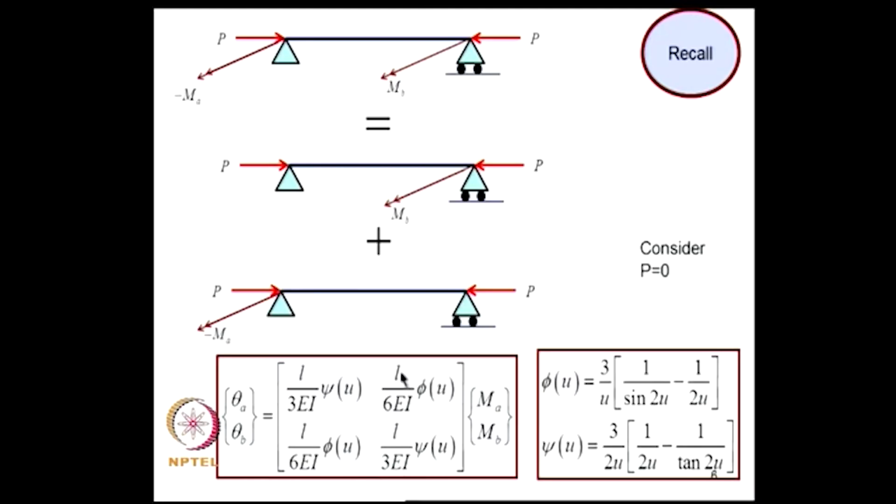In the limit of p going to 0, this reverts back to the traditional flexibility matrix, and in the neighborhood of p critical, these elements of this matrix become unbounded, thereby indicating critical behavior that should be of engineering interest.